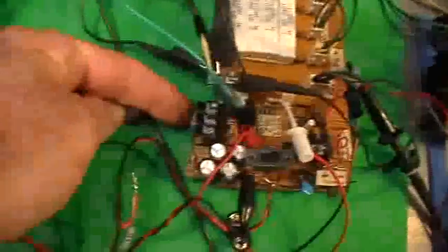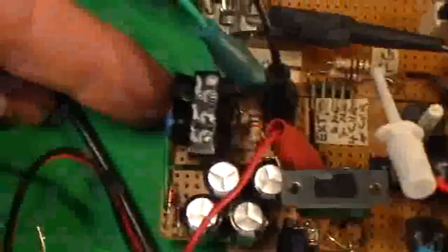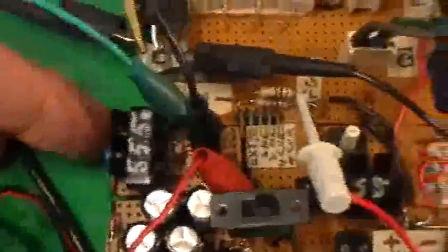There's the 9-volt battery. We're running the bias supply off of the lowest battery in the stack, and we're using my 555 voltage inverter to give us a pole that's more negative than the most negative of the battery. That output from that inverter is going into the potentiometer circuit, and that in turn is going to the board, bypassing the 50 ohm resistor on the board, because these batteries are not very charged.